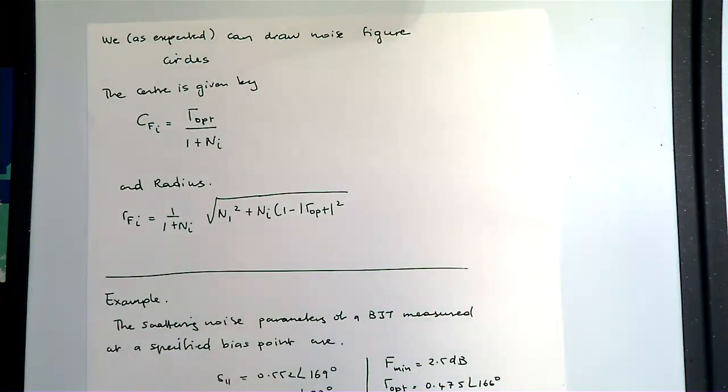There's always this capability of getting the maximum transducer gain or the maximum available gain. You can only achieve that at one particular point, right? But there might be situations where you're saying, well, hey, I don't need to have the optimal. What happens if I'm a little bit off? Like I've added a little bit of noise. What are the potential impedances that give me that particular noise figure?